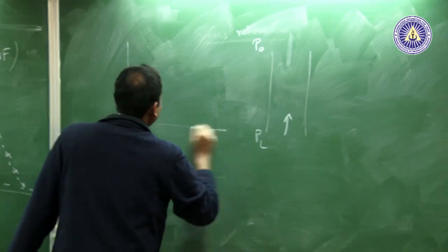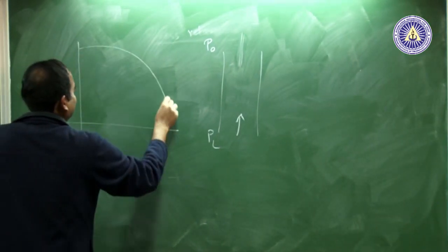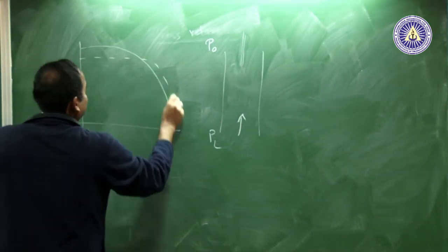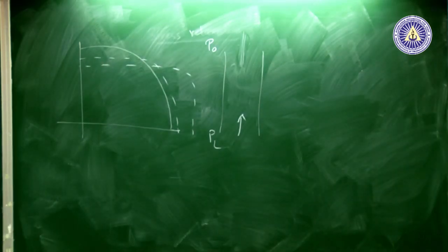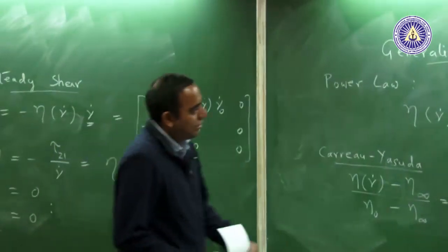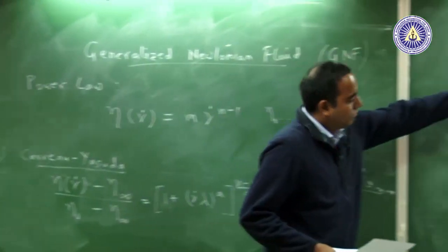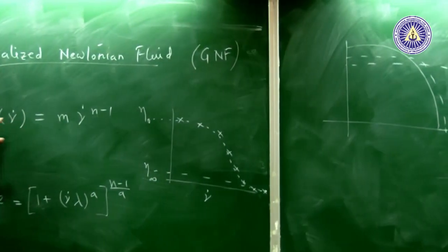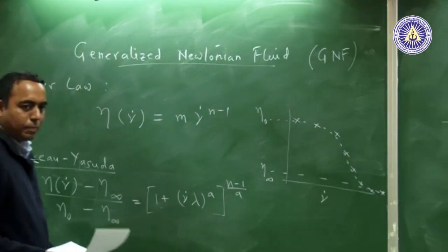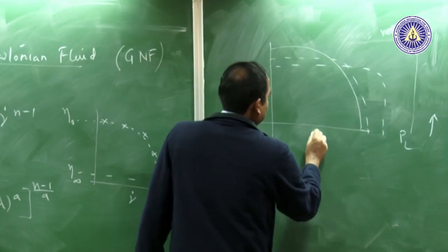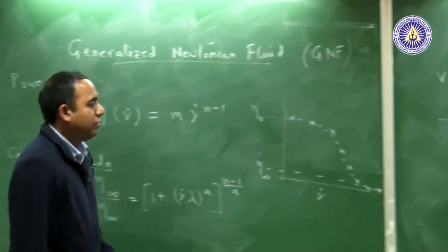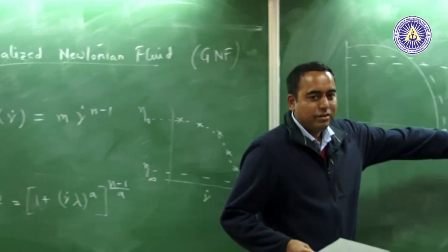Yeah. So, now I think I am consistent. So, power law would actually be like this. The higher the value of this index n, the flatter would be the curve that comes up. And in similar applications, it is not only pipe flow. This is V and this is R. And you know, there will be a no slip boundary condition at high R.